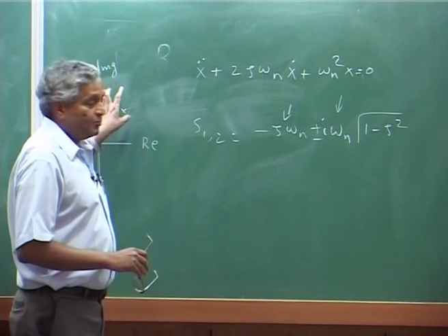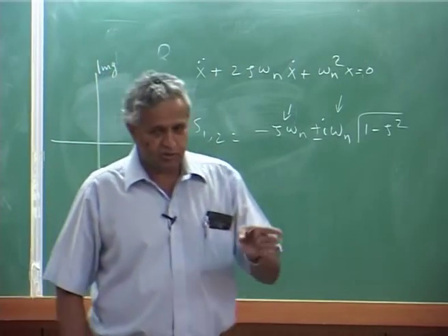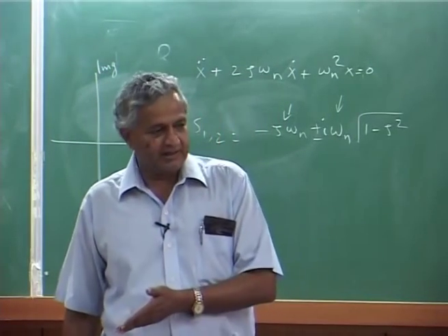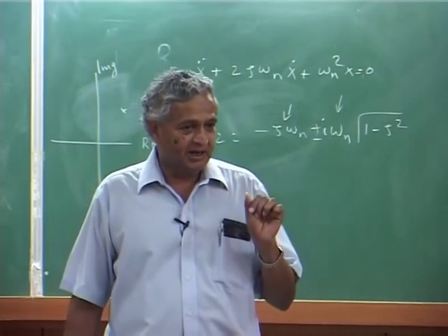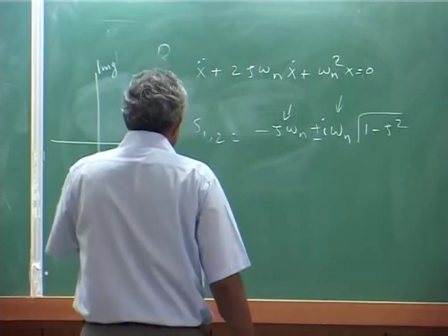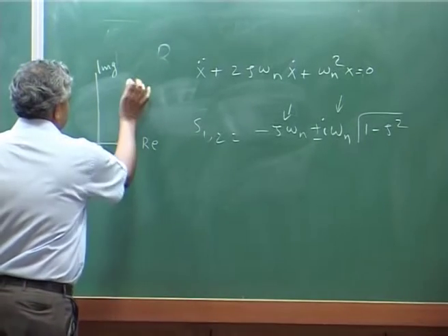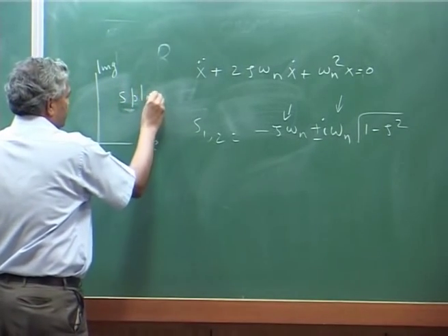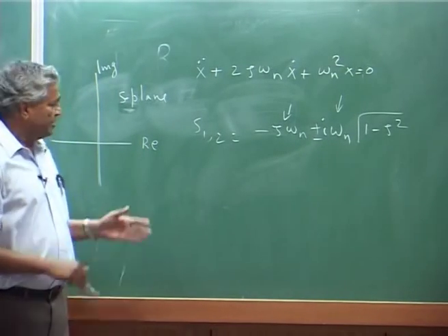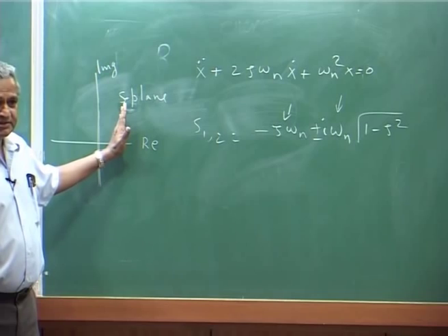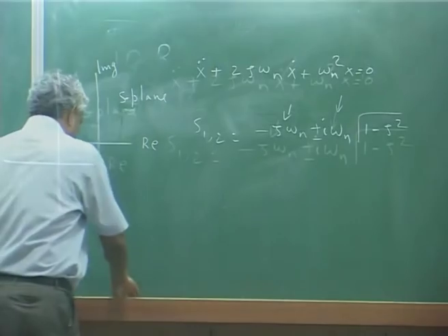Basically root locus is how the roots vary with any parameter, because this is a standard in control systems or even in flight dynamics, because in flight dynamics they will always want to see if I vary some parameter how my roots are. And you know that any root real part, if it is on the right half of what they call the S plane, the real and imaginary Laplace plane, the system is unstable, that is all. So, this is a standard root locus.